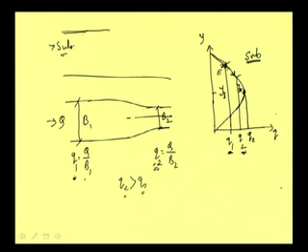So if our flow depth here is Y1, at this section the depth will be reducing like that, coming as a smooth curve. This depth will be Y2, and that is the situation we get when we contract this channel, for subcritical flow.